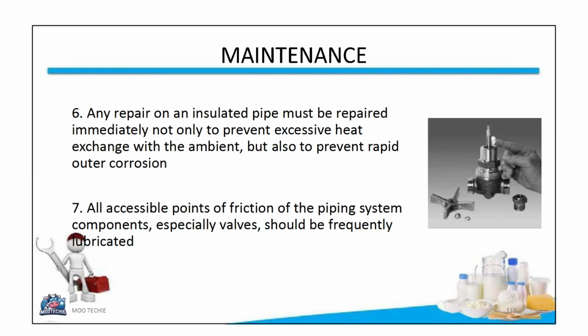Lastly, all accessible points of friction on the piping system components, especially on valves, should be frequently lubricated. This keeps them operating smoothly and prevents them from seizing.